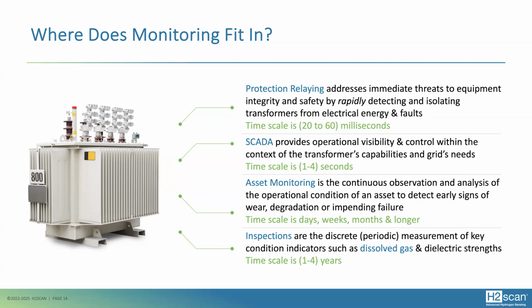If you're drawing an oil sample to get the dissolved gas status, that's this information. But you'll see how it's different from monitoring: it's discrete, it's periodic, and the time scale is usually annual, never shorter. There are a few exceptions, but for the large part.